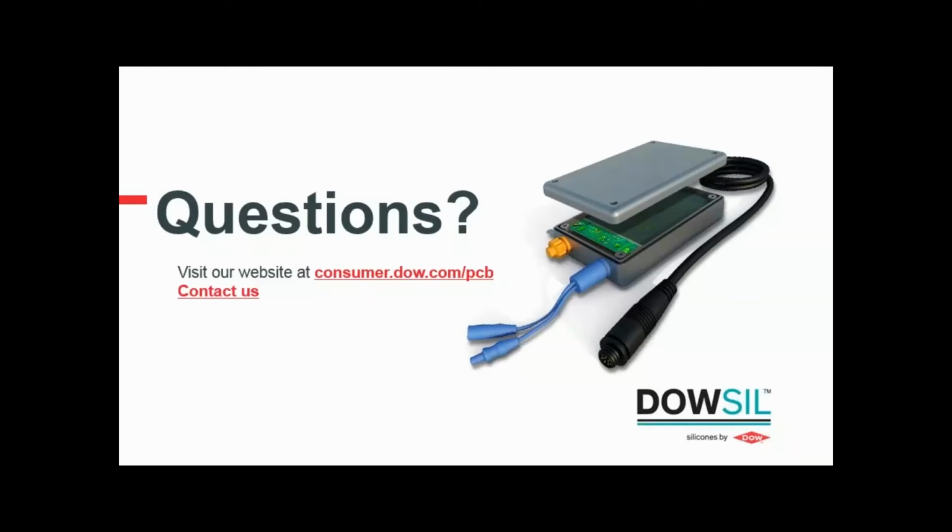The question is always if you get a certain adhesion on the conformal coating. But the question is as well, why you would choose first to use a conformal coating and later on encapsulate it or cover it somehow with another material. So in this case, this needs more explanation why this should be needed, because in my opinion, you would maybe just go for one material to provide both the protection of the lids and the insulation strength.